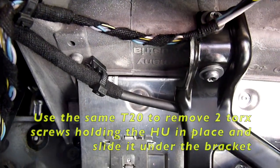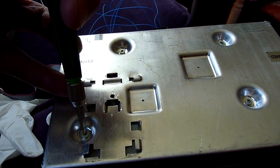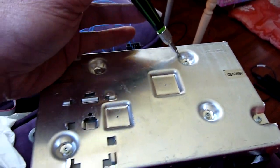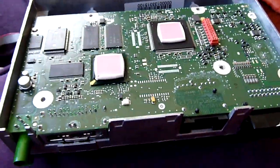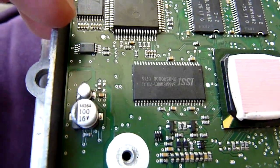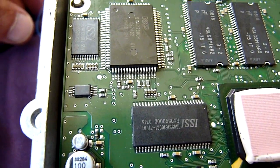So now we need to remove every Torx T8. And there's 1, 2, 3, 4, and 5. So you need to unscrew all 5 of these out. Okay, so when all of them are removed, you can just lift this up. And you can see your EEPROM is there. It's TSOP, which is a smaller size.